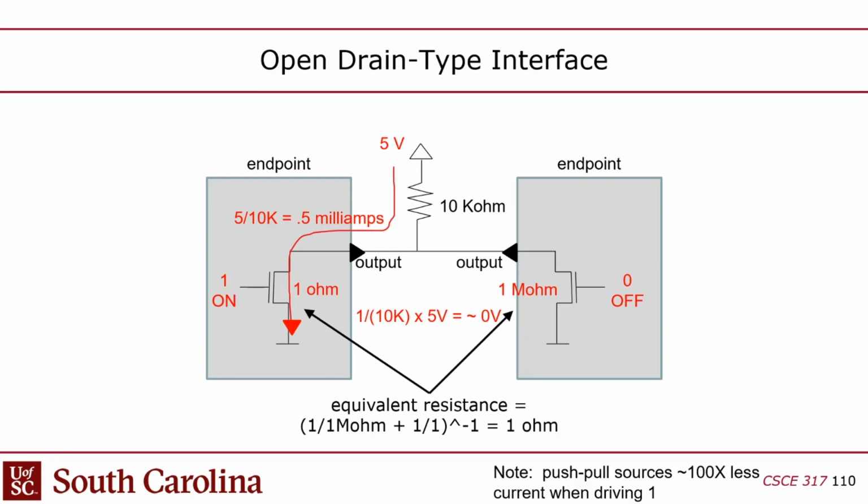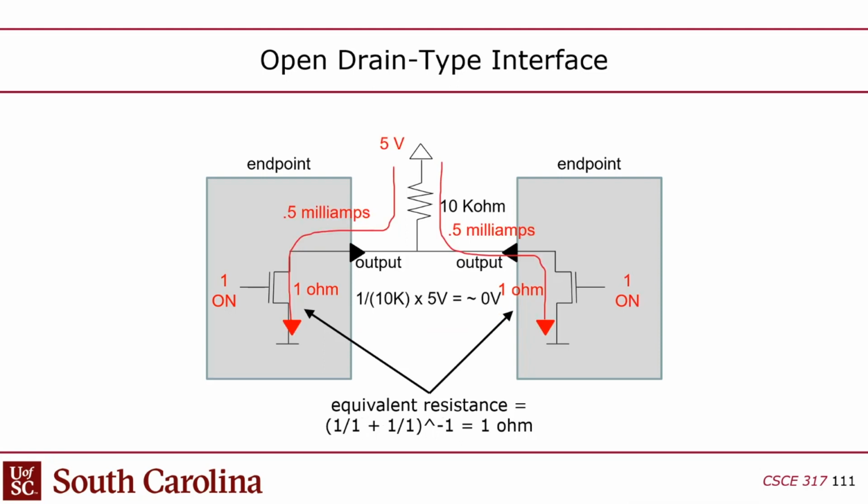Now we only require one transistor per output. You don't have to worry about the transmission gate, and you don't have to worry about the potential for there being a conflict, or at least a conflict that causes problems. If they're both on, then maybe 1 milliamp or so.